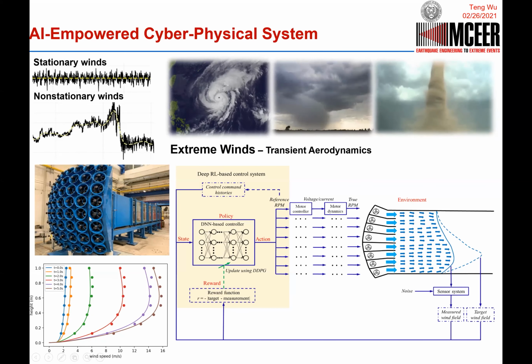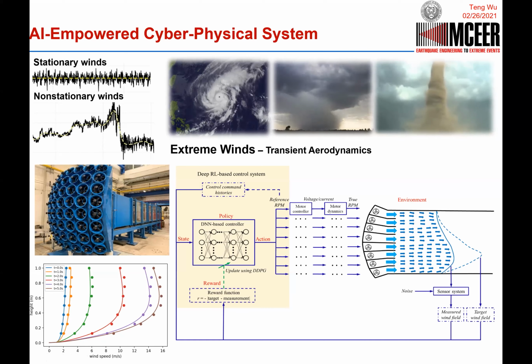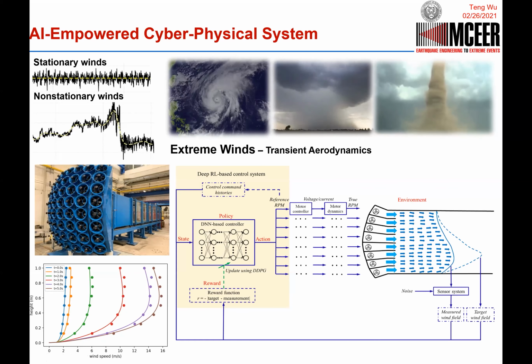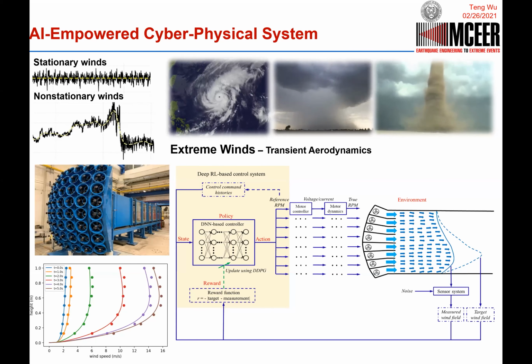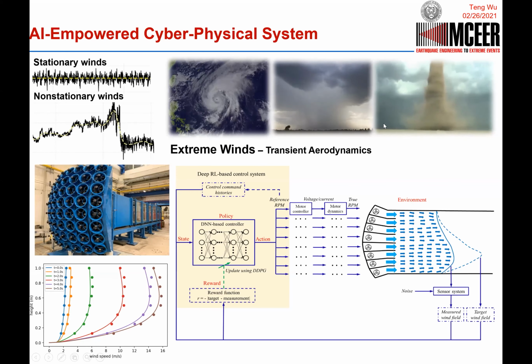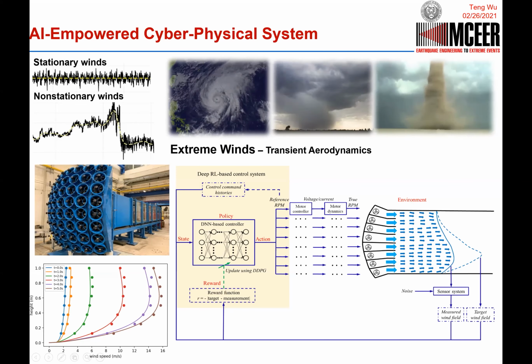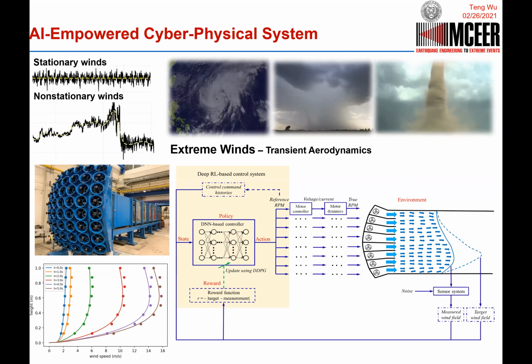The second is how to validate it, which is pretty straightforward because we always have a target. We just compare to the target, because in the wind tunnel, whatever kind of wind we want to generate, we tell the wind tunnel as our input. This target comes from our understanding of all those extreme wind systems, based on full-scale measurement data or meteorological knowledge.